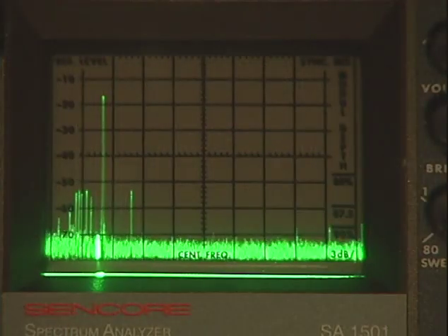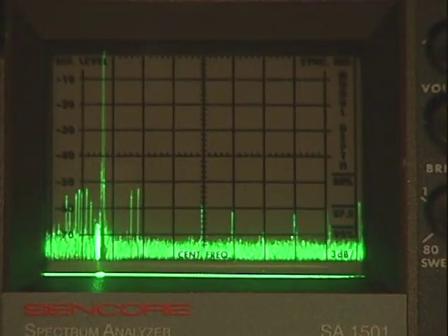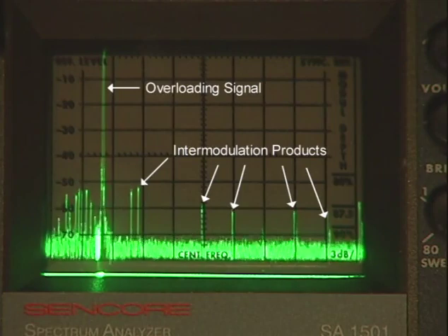You will need to pay attention to this spec when doing RF system design to be certain that the input level into an amplifier does not exceed its input capabilities. This can be tricky when the source is an off-air antenna and the signal levels can reach as much as 30 to 40 dBmV. Any signal that overloads an amplifier will create a number of nasty intermodulation products, unwanted signals, spread over a wide frequency range.